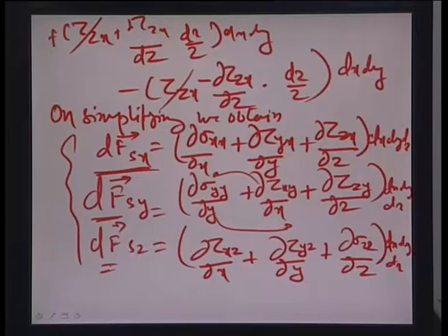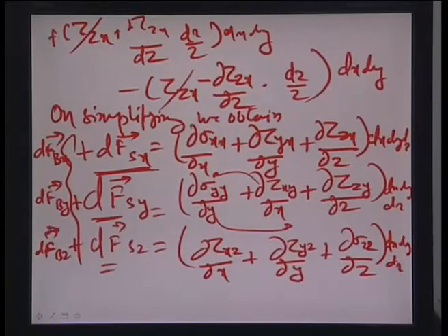All right. So, if we involve the body forces at this stage and try to figure out what the overall force would look like, we will have this equation slightly modified, because we will then have to add the body forces along the x direction, the y direction, and let us call that dFbx, b for body, dFby and dFbz, as the different forces.